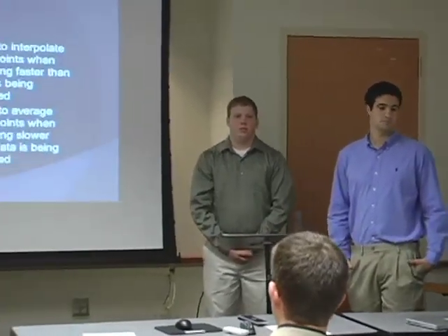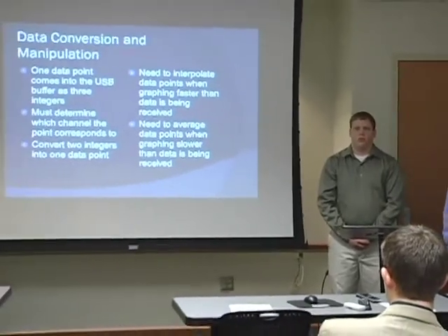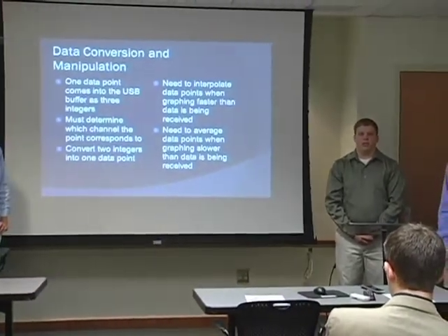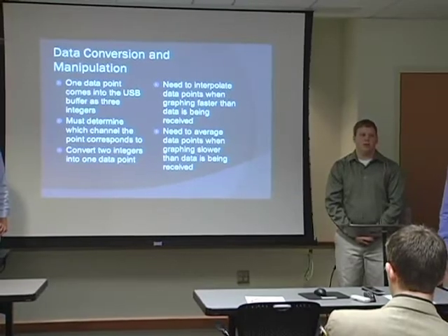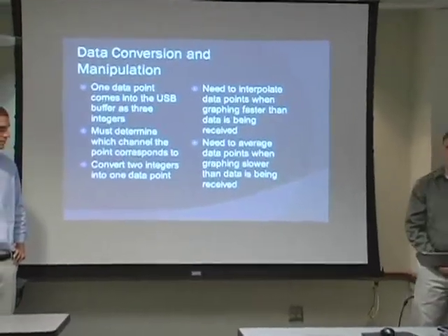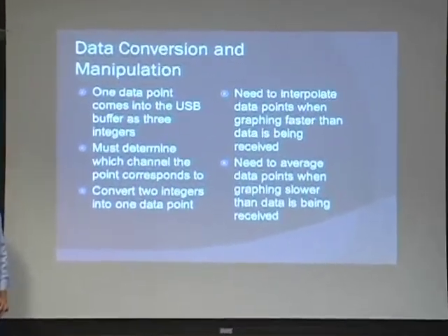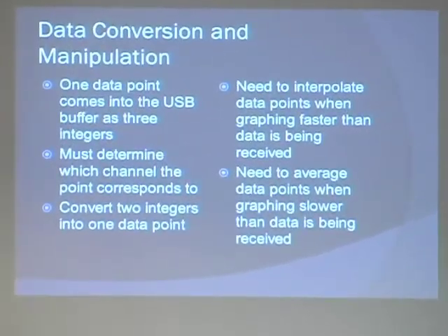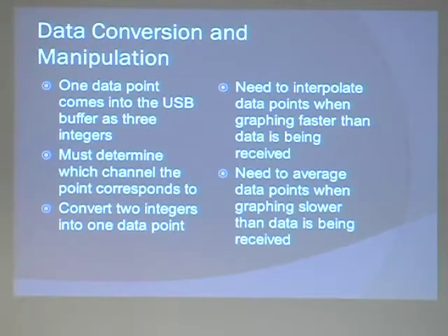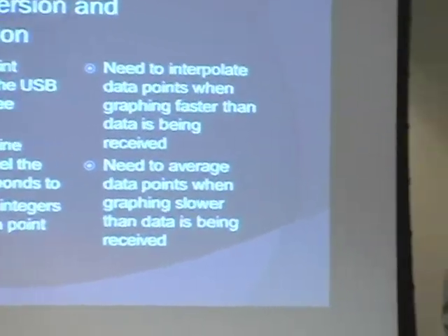Then from there, my goal was to read in the data points from the USB buffer. As Alex said, we had to read 5 bytes from the buffer to include the stop bits. That slowed down our graphing significantly because it took more time to read the points in. To increase our speed some, we multi-threaded our program. We have 1 thread running to do the graphing, 1 thread running to convert the data points, and 1 thread running to read them from the buffer.